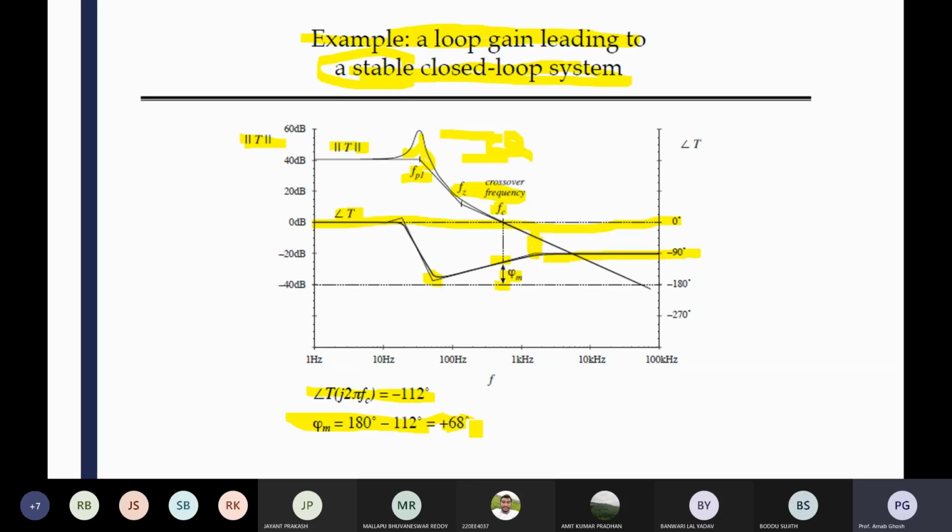So your damping factor, in my experience I am telling you, there is no hard and fast rule, is coming nearer to 0.68. Okay, it is from my experience I am telling you. So 0.68 means it is not critically damped. It is an underdamped system, but it has less magnitude, and you can see the direct effect on your Q factor. High Q factor means it is peaky in nature. For low Q factor, the peak is quite less.